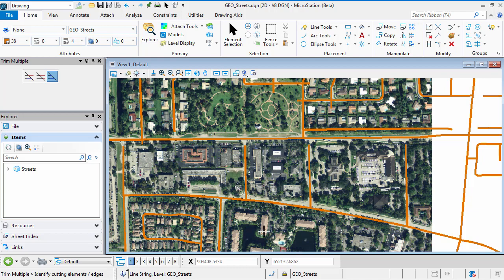So the first thing I want to do is, where do I want to go to? I want to go up to this element here. So I select this line up here, and now I just drag. Oh, let me make sure I didn't get that there. There we go. Now I can drag with holding my left mouse button down and dragging. So keep the left mouse button clicked. Now I'm going to let go of the left mouse button after I've dragged a line through all of the elements I want to extend. And there they go. So that was really easy. I did multiple lines with a simple drag line.